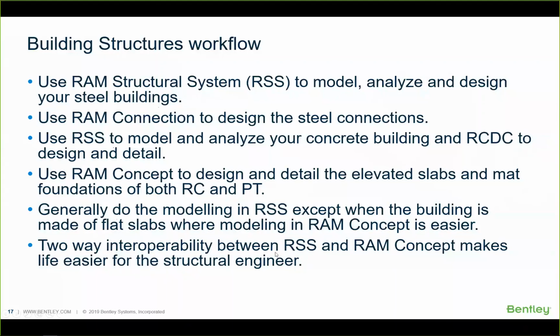Two-way interoperability between RAM structural system and RAM Concept makes life easier for the structural engineer, particularly when the slab is made of post-tension. The post-tension forces on the slab will impact the column forces, which need to be updated in the 3D model in RAM structural system. So the two-way interoperability is very important for this workflow.